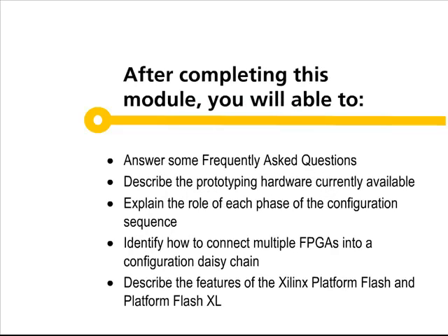After completing this module, you'll be able to answer some frequently asked questions. You'll be able to describe the prototyping hardware we currently provide, explain the role of each phase of the configuration sequence, identify how to connect multiple FPGAs into a configuration daisy chain. This will allow you to configure a device from a single PROM. And you'll be able to describe the features of the Xilinx Platform Flash and the Platform Flash XL devices.